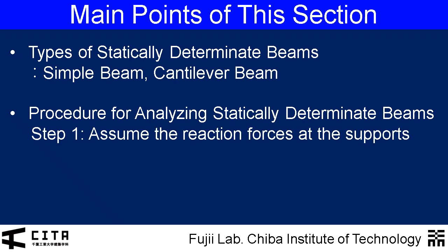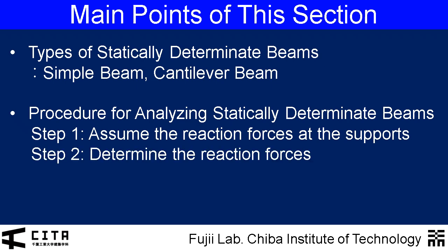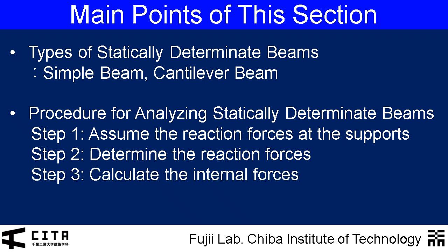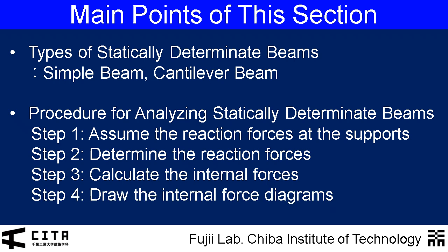Step 1. Assume the reaction forces at the supports. Step 2. Use the equilibrium equations to determine the reaction forces. Step 3. Calculate the internal forces inside the beam. Step 4. Finally, draw the internal force diagrams.